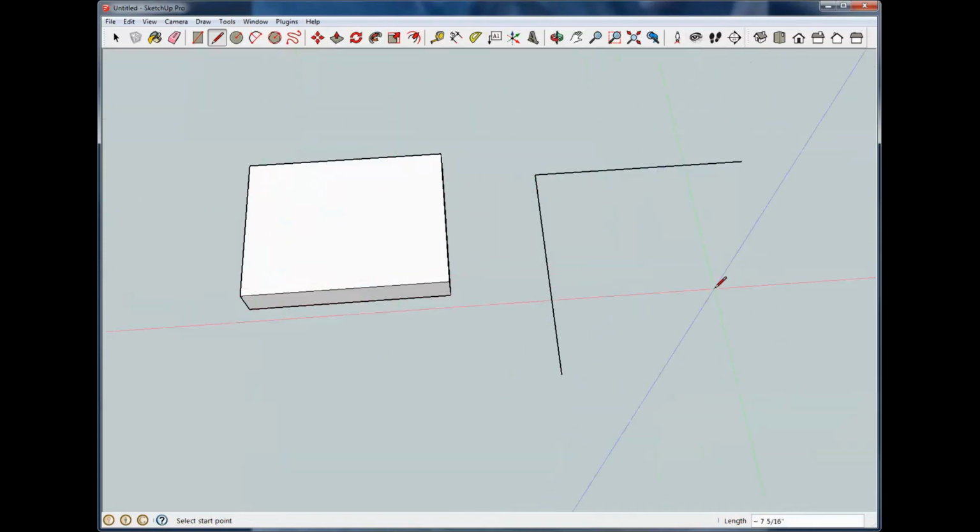Typically, you can use offset tool on a single line, but if you click on offset, you'll notice that we get a little international no symbol. Even if we highlight it and go to offset, it means you can't do it. It needs to be two entities that intersect, a face or an arc. I'm not sure of all the idiosyncrasies with the offset tool, but I just want to give you this much information. If we select this and then go to our offset tool, it'll work.